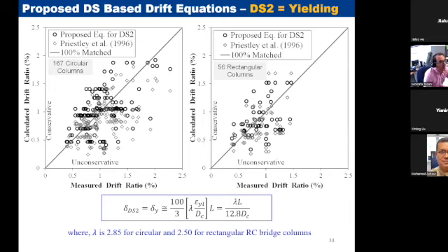Very good question. We went with all test data, and usually in test, as you mentioned, they're all fixed base. We did not change these numbers based on the fixity or basically anything like that, because our goal was again to do a quick demand analysis at this level. You see this damage. This damage is related to 5%, 4%, 5 inches of displacement. So that's actually what we did. We did not soften the model or these parameters to include soil or soil structure interaction or anything like that. So these are all based on fixed base. Okay, thank you.